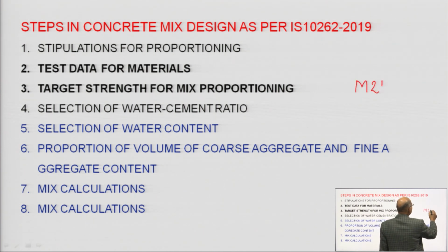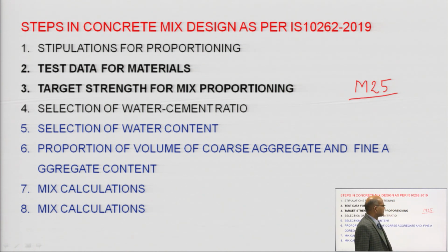concrete. Because concrete is not very homogeneous in nature and different steps are involved in concrete processing, we have to give a certain margin, because quality control at each and every stage is not always possible properly, or the contractor may not be of very good quality. So, you have to increase the mean target strength. That data is required.